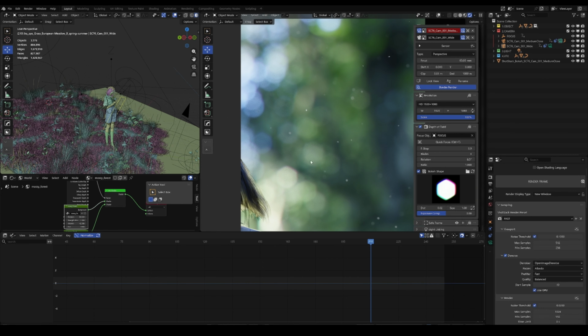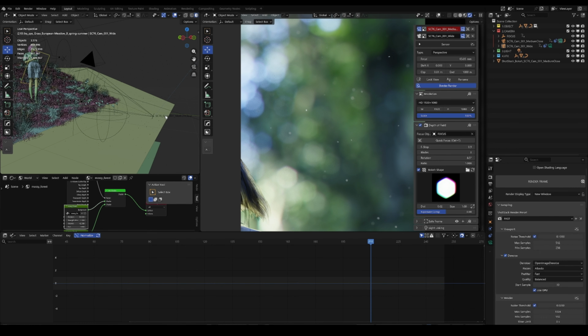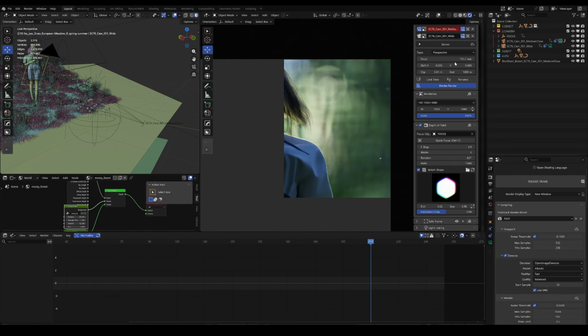At the same time, since we are using physical principles, creating a plane in front of the camera and then using pinhole imaging, we are directly affected by this effect, which is influenced by the aperture and focal length. At this point, we need to manually fit it again. After we adjust the focal length or aperture, you can see that the shape of the light spots has become problematic. We simply click on it once, and it will automatically adjust and adapt to your current focal length and aperture, achieving a very beautiful bokeh effect.